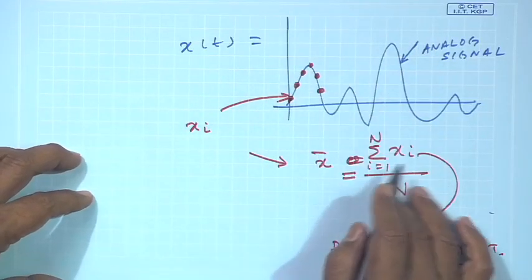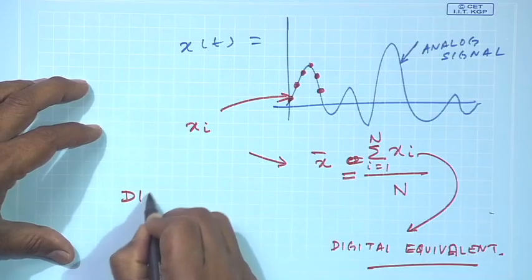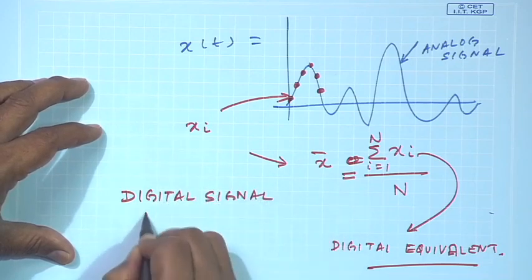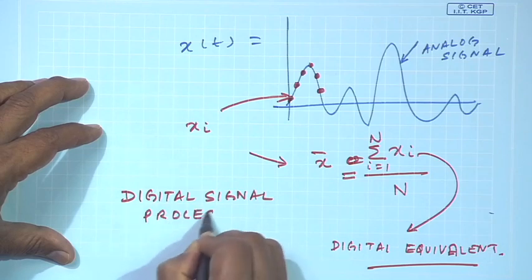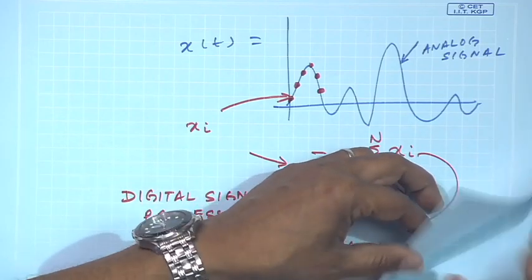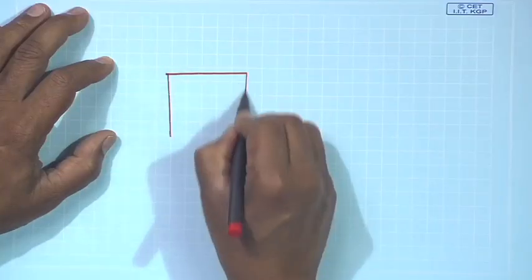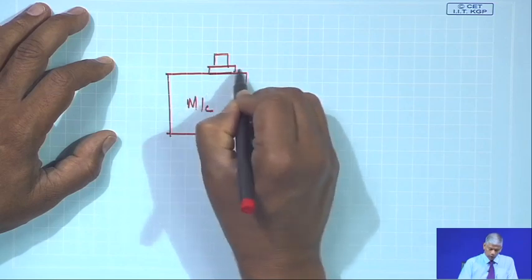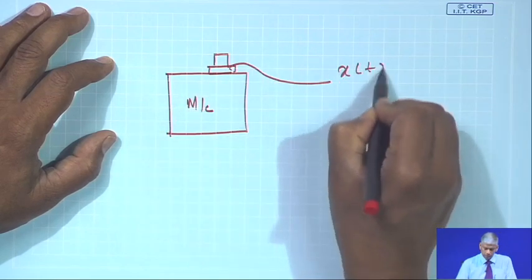so that all these numerical computations, be it just finding out the features, even finding out the frequency domain coefficients of such a signal, we can do that, and that is actually what is done in digital signal processing. And just to recap, as you know, in CBM, our machine's condition actually depends on what we infer from the signal obtained by this transducer, x(t).